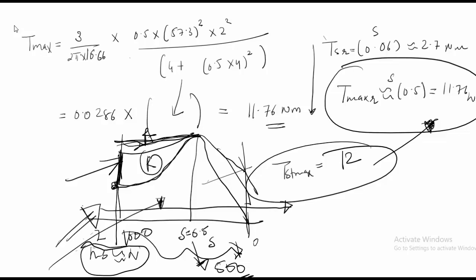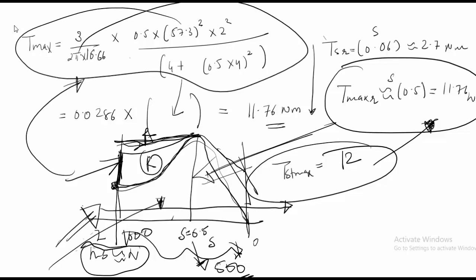So if you plot this graph for different slip, it will look like something, and exactly it can be found out by substituting the different values of slip in this equation and plotting it against the torque. So that will give you the T versus S curve for a machine. So that is how the torque and the slip are related.